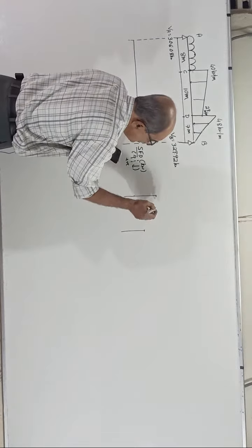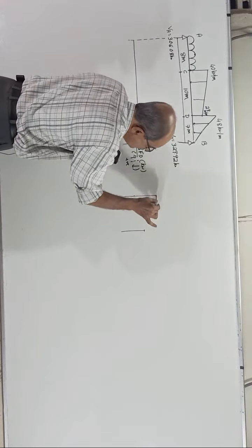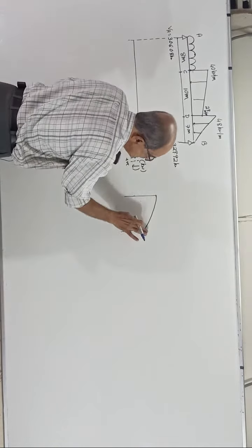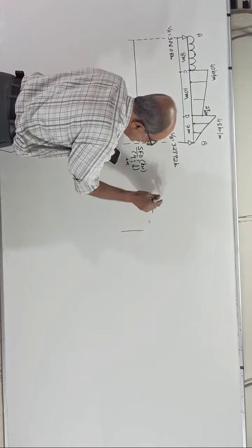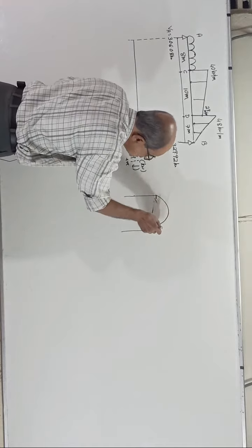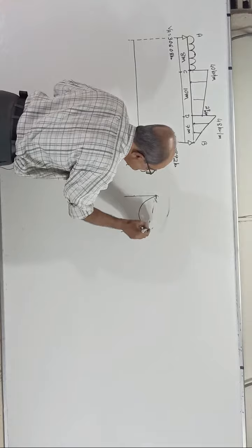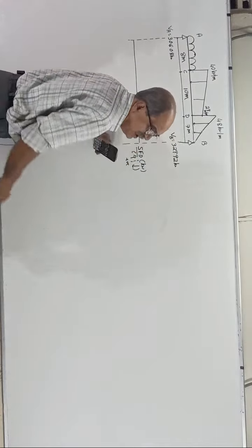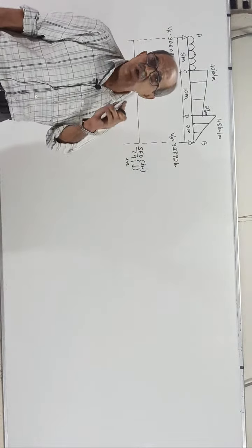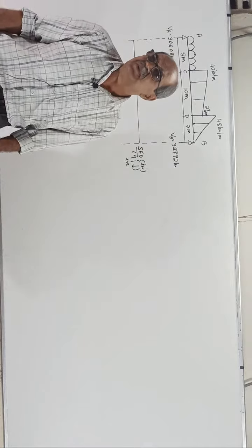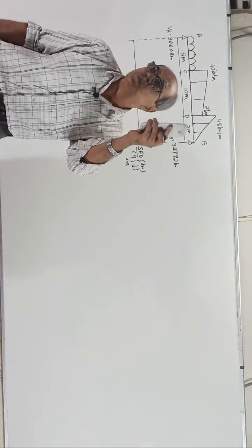But if a parabola is there, for example, someone will tell you to join here to here by parabola. I have got so many options. One option keeps on dropping. Second option goes up and then comes down. One more option comes down and goes up. So you cannot tell that way. Therefore, when curvature comes for either SFD or BMD, you have to see the slope.